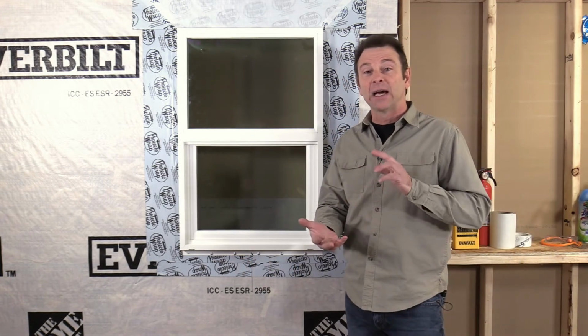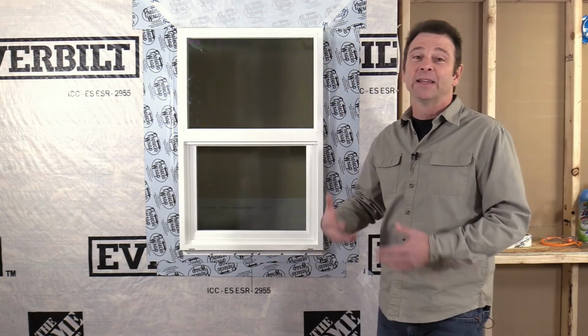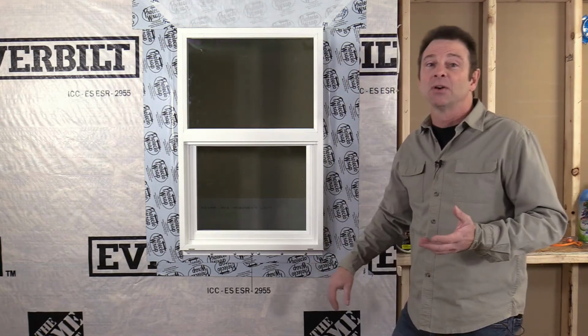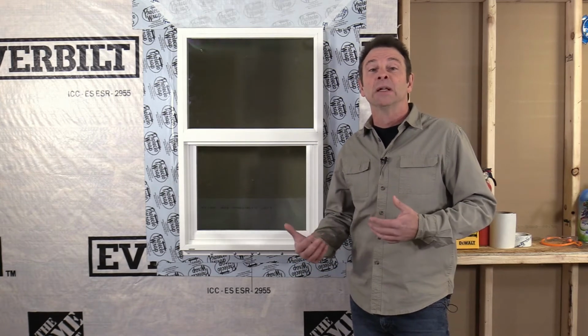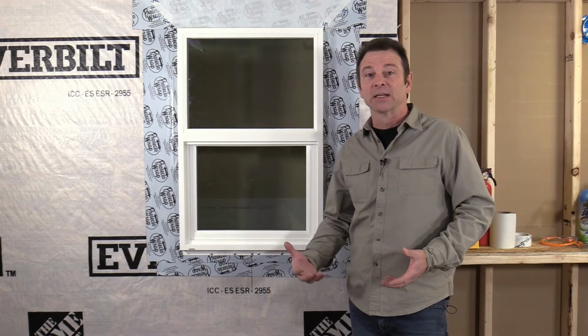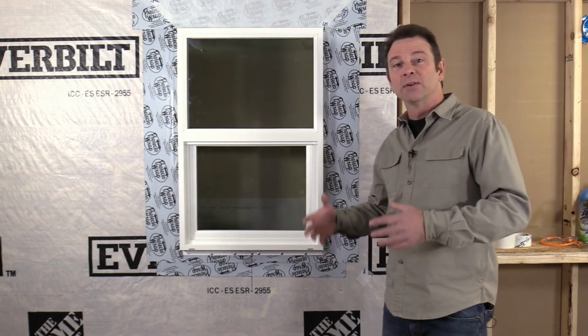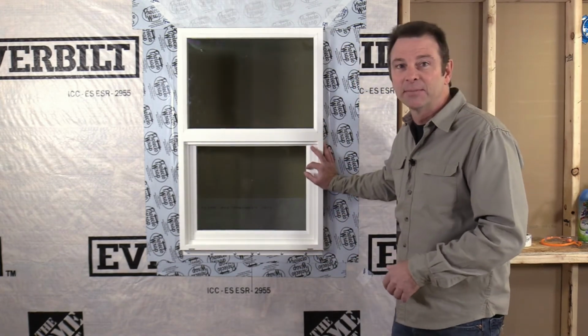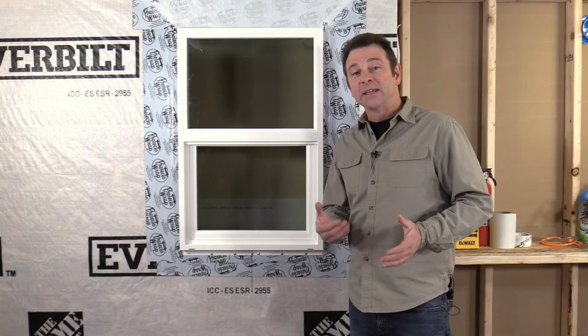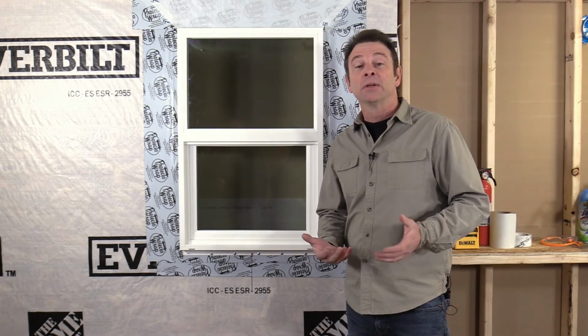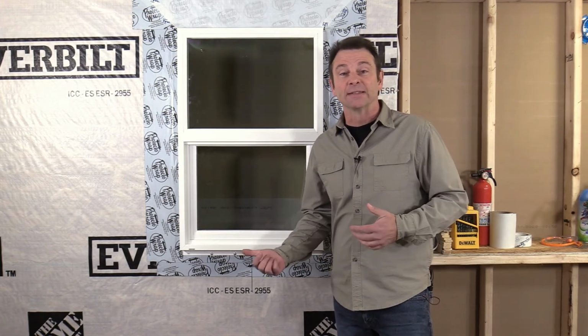So you have to not only look at the spec, but then measure your slots or holes and then figure out what keeps you within the parameters that they're giving you. All of this comes into play, and your installation crew needs to understand these things because they affect the way the window stays true, how it seals to the building, and how it stays operational. Along the lines of the instructions or specs from the manufacturer, they often spell out more than one fastener that's approved for this installation.